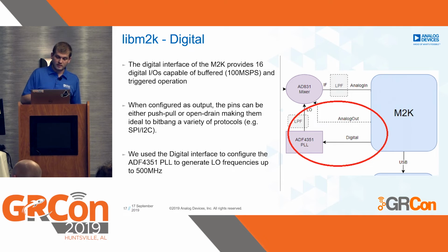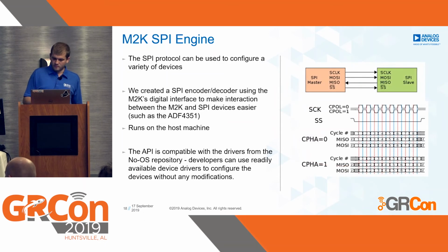In this project, the digital interface was used to configure the ADF4351 PLL in order to generate LO frequencies. Like I said, the ADF4351 has a SPI interface.